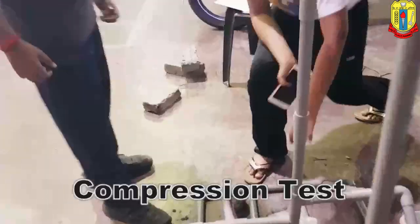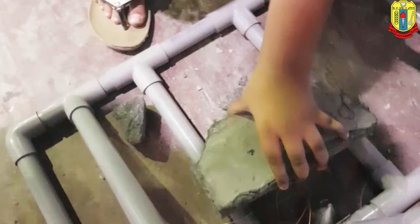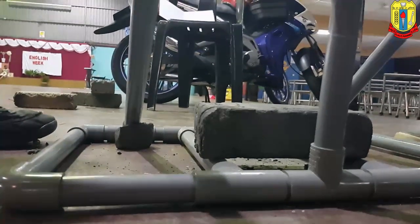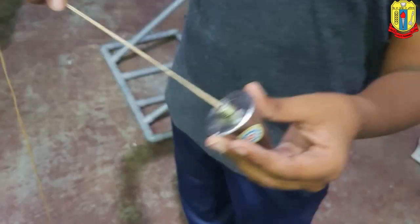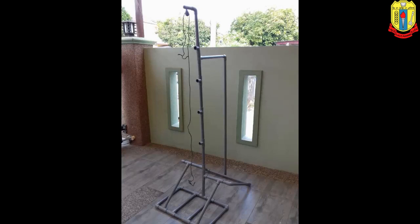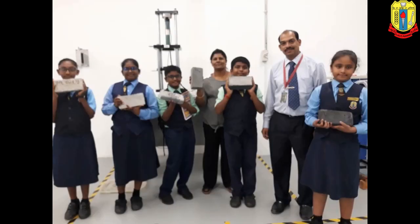Compression test. Compression tests were carried out in 2 methods. A test was designed to test the brick as below. Compression test in school: PVC pipes were fixed at 6 feet height. A weight of 300 grams was tied to a string and passed through a pulley. A brick was placed at the bottom of the PVC pipe and the weight was dropped to hit the brick. The impact on the brick was recorded. The same method was repeated for other bricks.